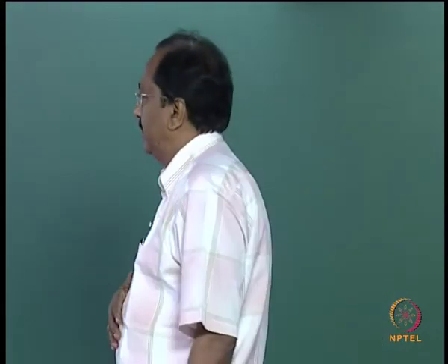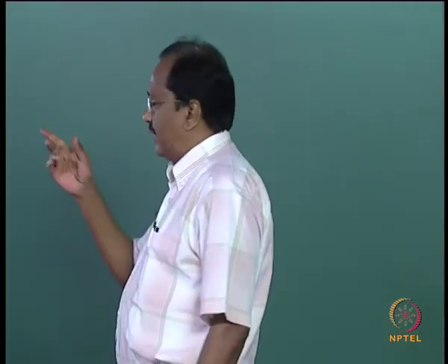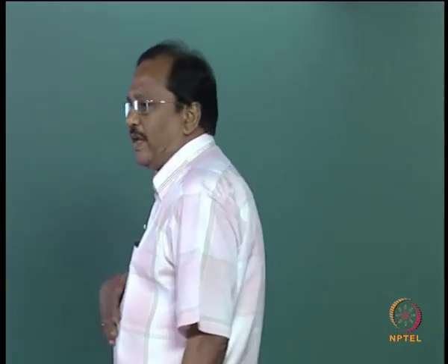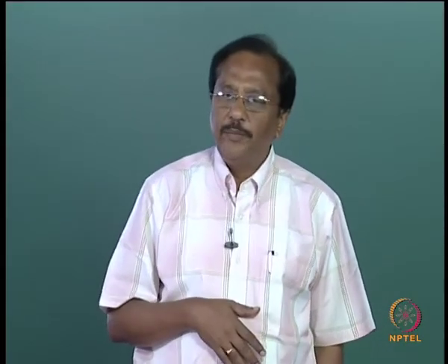There are several formulas available in literature apart from the criteria which we have seen. For example, McCowan's relationship is widely used. What is the breaking wave height? It can be easily said to be approximately 0.78 times the water depth.